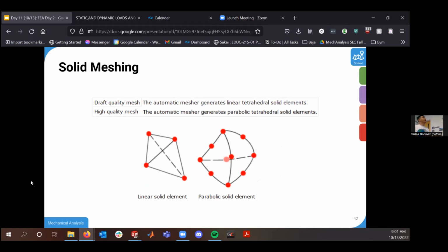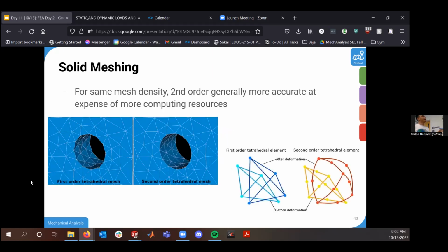If you have any weird curvature in your design, you are going to want to use second degree elements, at least for your final analysis, because first degree elements have a bad disadvantage where they can't bend at all. The connection between the two will always be straight.